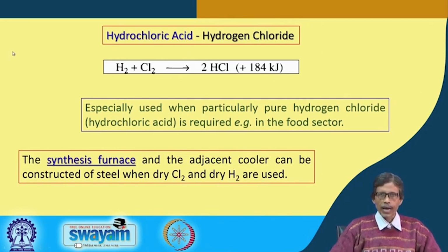So we have to have dry HCl and dry hydrogen gas, because it should not be moistened. That means the product of this reaction, the combination of these two gases producing the corresponding HCl, should also be dry. Because if we have some doubt that the gas produced has some moisture, we should try to avoid that moisture also. So we must have some drying column or moisture trap on the outgoing gas leaving the synthesis furnace.